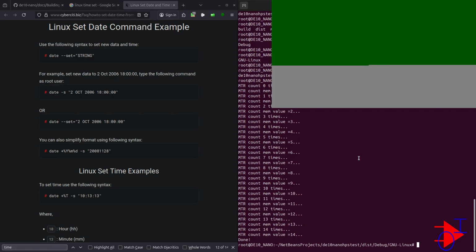So eventually I have to disable the console output from this UART port, and what I will do is open that port from the C++ program and read that port and then receive the traffic, just like I have the Arduino driver program to do. It receives commands over the UART connection, and it then performs the actions based on the commands.